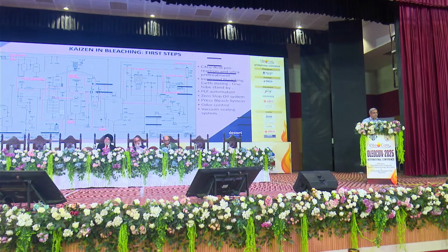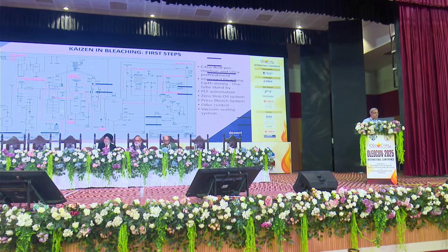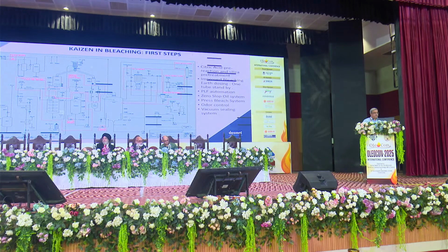Similarly, washing can be entirely eliminated by a silica pretreatment section, which is already implemented in many plants, but there is still scope to implement the same. One important thing is the vacuum sealing system. There are frequent power failures in the plants, and every power failure leads to loss of vacuum, which can be avoided by a vacuum sealing system, which basically consists of on-off valves in the steam, spark steam and cooling water lines, which seal the vacuum in a standstill condition.